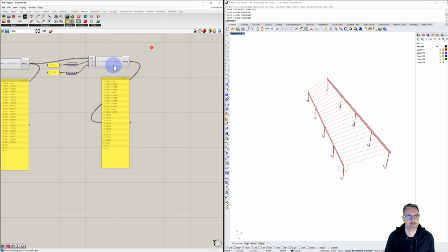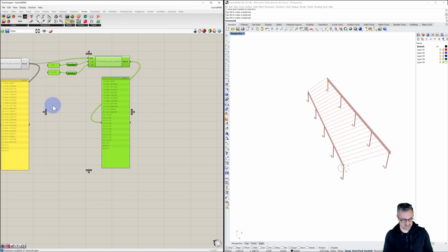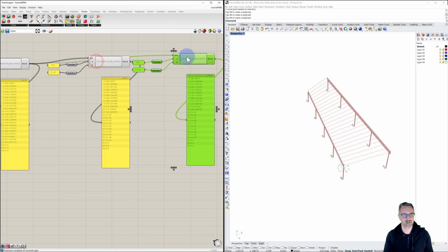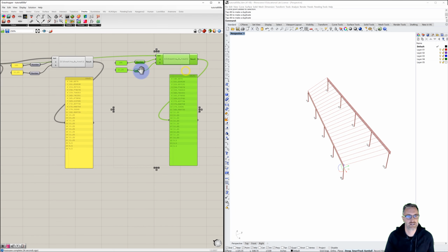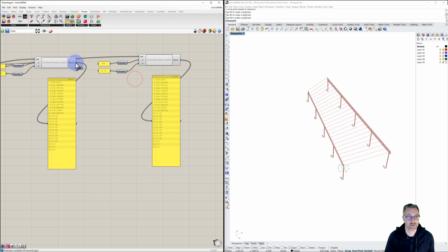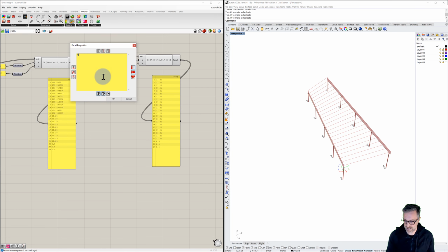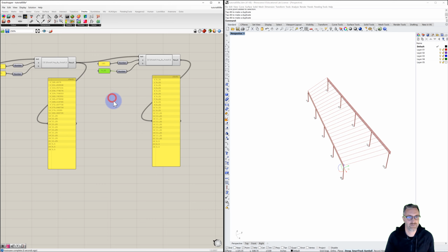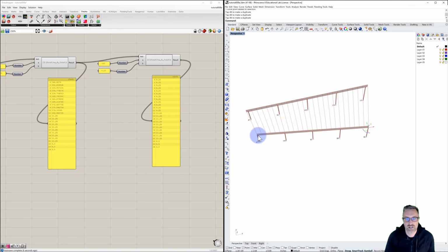We're just going to do this a couple more times as we work our way down to a 2x6. And so the next set of values, and we have to remember to pull the result into the test. This time 185 becomes 145. And the depth that we'll replace it with is a 2x10, which is 9.25. And now we see all the rest of the things on our list turned into 9.25, but we have a few more to go.